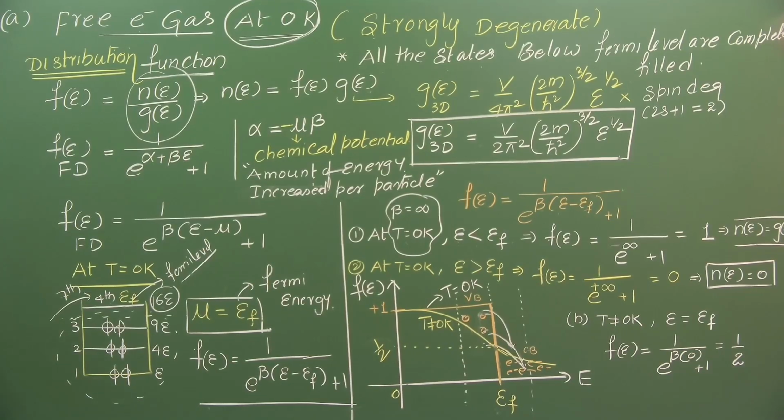Is it correct? That side conduction, this side valence. Where you are getting holes is the valence band, na? Sorry. Correct. Where electrons are filled is the conduction band. In an intrinsic semiconductor, the Fermi energy level lies exactly in between the conduction and valence band. If it is a p-type material, the Fermi energy level is close to what?